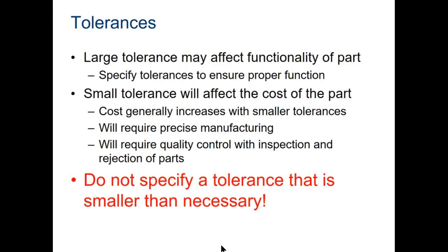If your tolerances are too large, it may affect the function of the part. You've all bought those cheap pins that look like a big pin, but they're not a big pin. Sometimes the little pin that goes into the tube that holds the pin together is too large, or too tight, and the barrel cracks. And sometimes it's too loose, they're not close enough together, so the little pin part tends to slip out and fall out.